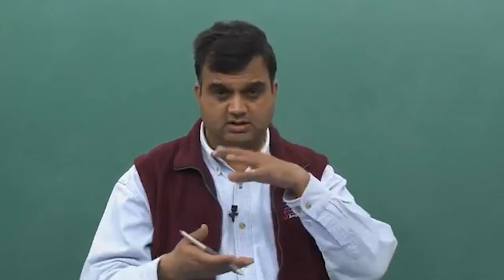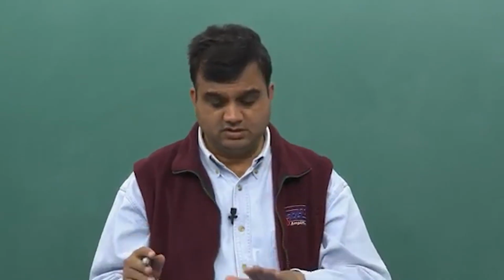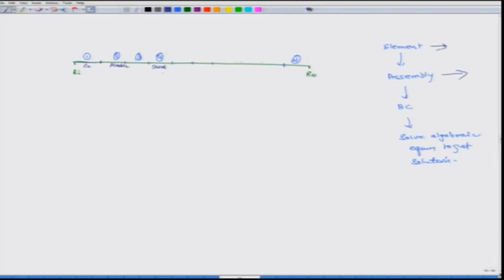And then when you are doing assembly, it does not matter. All you are doing is adding some constants here and there and coefficients of different things. So at assembly level, you don't worry about that. At element level, you compute element by element the terms of that matrix, and there you handle the variation of material properties relatively easily.